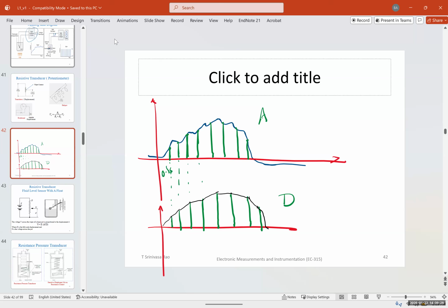Okay. Now you see that the analog on the top and the analog that we reproduced after analyzing the digital is a little different. That is because of the sampling rate. So if our sampling rate is too far apart, imagine if I had a sampling rate that looks like this. I have one sample here, one over here, and one over here. Then my signal will look like this.